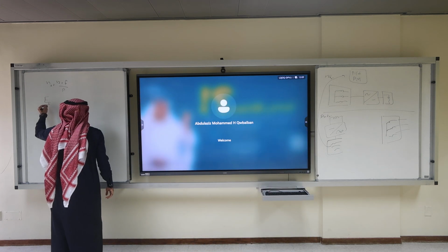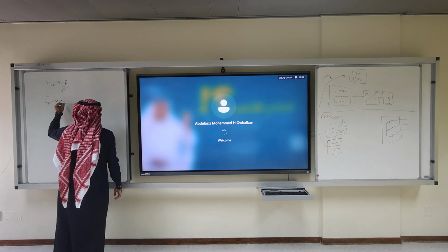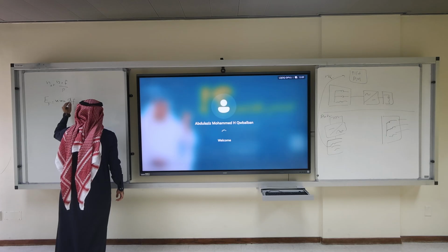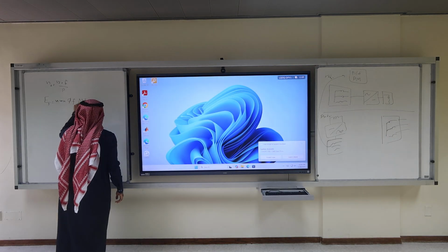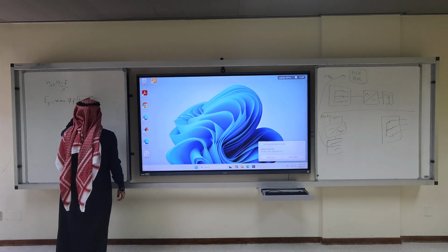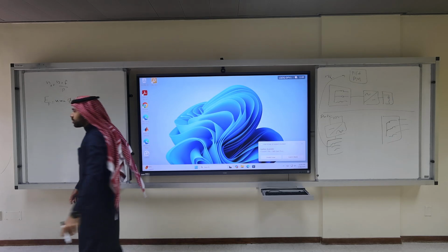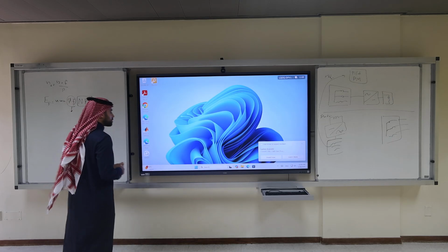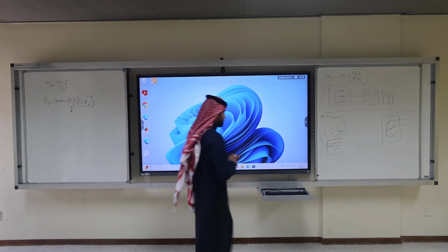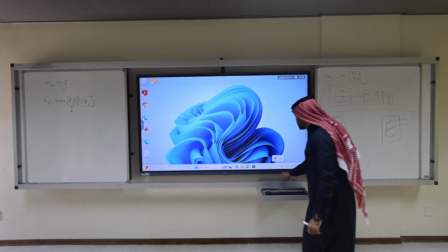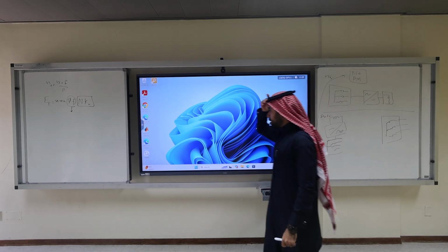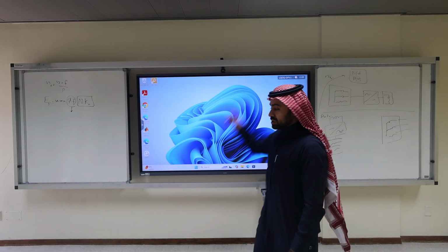And what was the formula? 4.44 times flux, speed, N windings. We said these two are not in this course. The only thing you have control over is either the flux or the frequency. Okay? What else did we talk about?